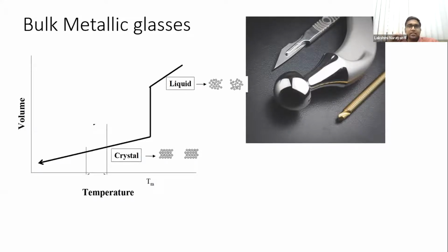Okay, we need to understand it from a solidification point of view, from a physics point of view, what it is. So if you have a liquid metal at high temperature, and you start cooling it down slowly under equilibrium or semi-equilibrium conditions, what you generally do in a casting is cool it down, and then suddenly there is a change in the volume. Okay, there's a very big shrinkage that occurs, a reduction in volume, and there is a discontinuity in this curve, right?